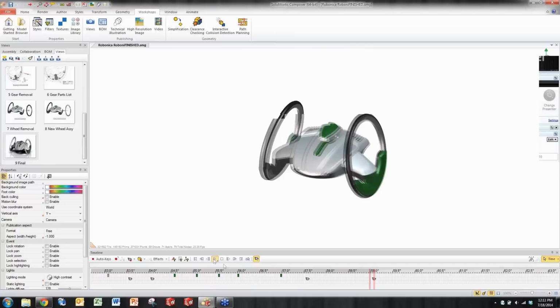So when we create animations, we do have the ability, for huge time savings in Composer, to take the first portion of the animation and flip it around. So if we're disassembling to start, we can basically just flip it around and create an assembly procedure all within one animation timeline. So this came to about a minute-long animation. I'm going to only end up creating about 25 to 30 seconds of animation, and then we'll just copy the rest and flip it around.